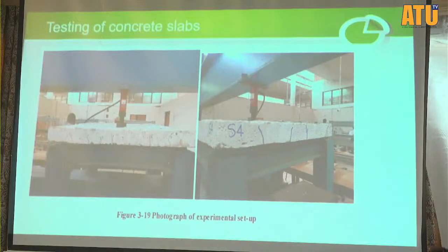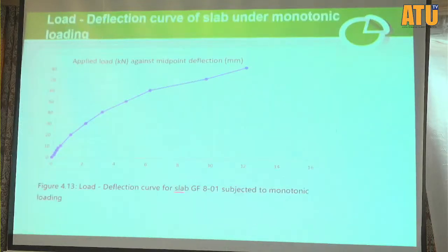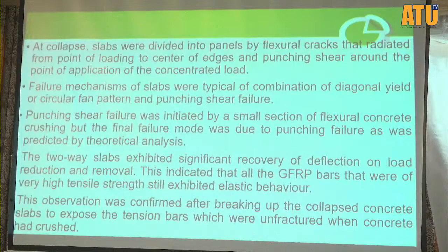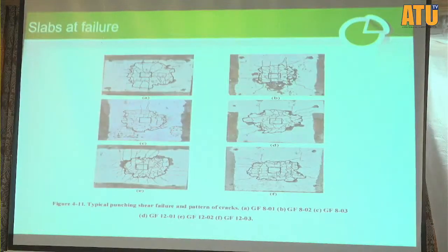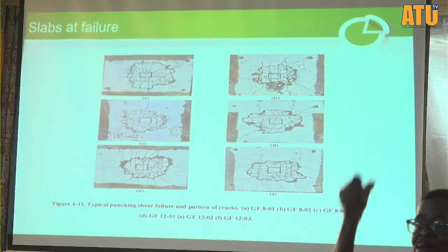Low point load in the middle. So maybe in the real application, we will have a flat slab, so a column in the middle, no beam. So the findings from this research can be applied when we are dealing with a flat slab, because the major finding is that the problem is with punching shear around the point of application of the load, which is like a flat slab.